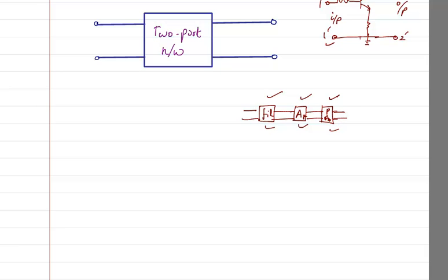And suppose this goes through an antenna, so the antenna can be represented by a single port network. So here you have a two-port network, here a two-port network, and the final antenna is a single port network. So this whole circuitry can be analyzed if you draw each of the individual parts as a two-port network. And that is what most engineers do. Whenever they want to make a circuit, they make it in parts and then try to join them. How to join them we will understand in the fifth module.